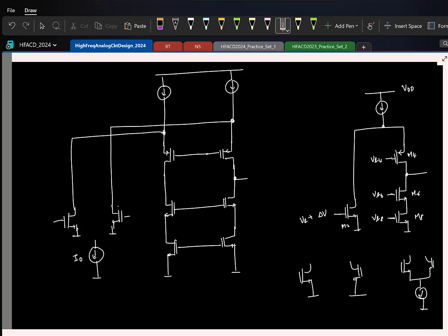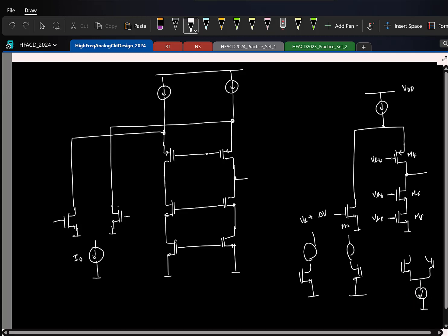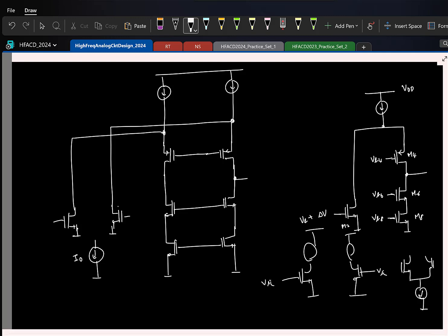I mean, if you do it like this, right? Let us say I have a differential amplifier like this. Okay, I've drawn it very badly, but okay. Even if both of them change by the same factor, both outputs are going to change. But we don't want that. We don't want our amplifier to respond to common mode changes. We want it to respond only to differential mode excitation. And the current source here will help you in that. So please go and check the calculations we did for the common mode response. There we would have found that only if we have an infinite resistance looking down, the amplifier rejects any common mode changes.